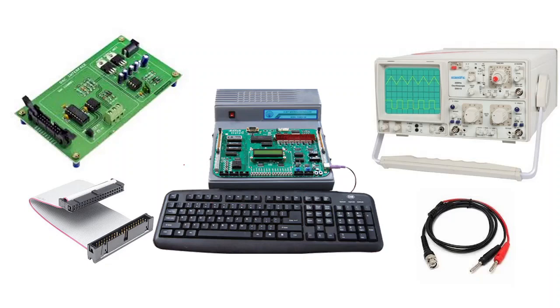This slide shows you the physical hardware connections, and this is the kit which is considered as microcontroller 8051. It is operated with inputs given to the kit using the keyboard, so that we can see the coding here. It stores the coding here, and then these are the bus connections extension given. Using this bus cable we will connect the DAC kit. This is the DAC kit, DAC 0808. We'll interface the cable here, and then it is connected to this. So this is the interfacing procedure.